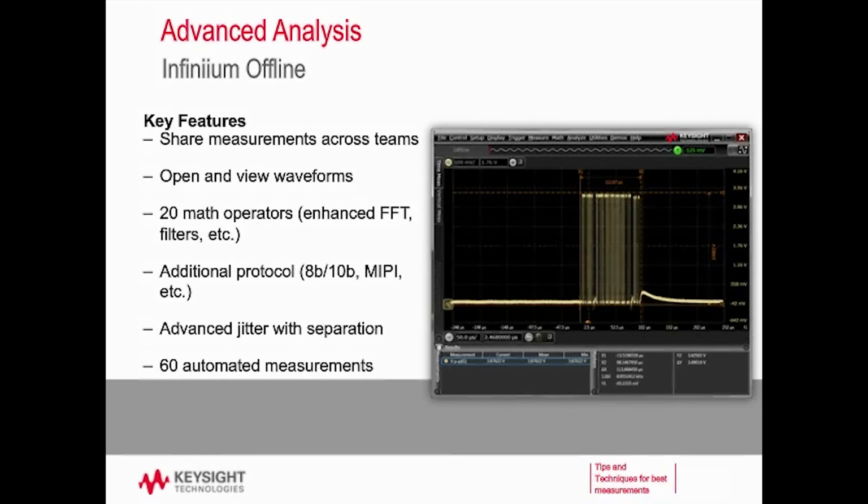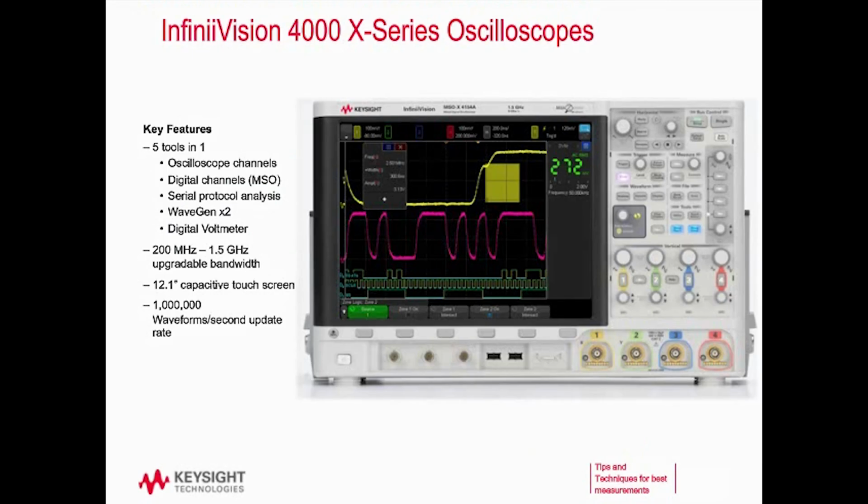And that's going to help you make better FFT measurements. We also have some additional protocol capability and analysis, and we do some advanced jitter and separation. And just like our Infiniivision scopes, this does automated measurements. So again, let's look at the scope we were using.